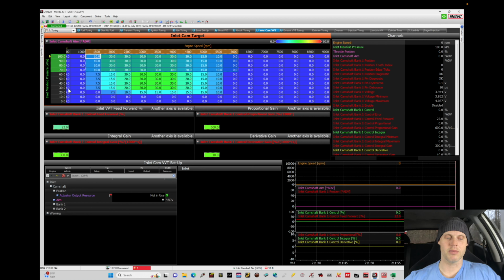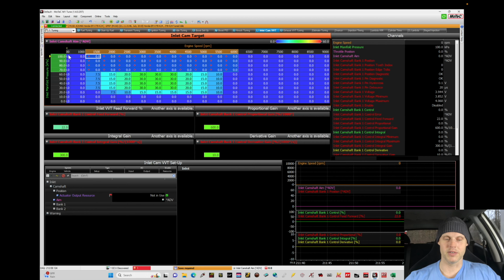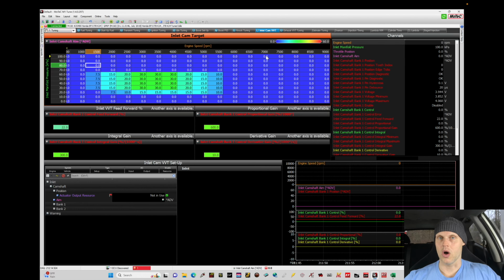What I'm going to do is just set my inlet manifold pressure here from 70 kPa and above to 0. So we're going to zero out what we've done on the low cam, and we're going to do a pull on high cam and figure out as a baseline where we're at. We're going to adjust our estimate table values based around VTEC being on at that 0 degree, and then we're going to just do pulls and walk up the variable cam timing and figure out what is going to be optimal for this engine. Usually at high engine speeds, we're not going to roll it back to 0. We might roll it back to something like 20 or 30, but in the mid-range we might have as much as 50 degrees if you have a 50 degree VTC gear, which I actually have installed on this engine with OEM cams. So this is how we prep things to do our base pull.